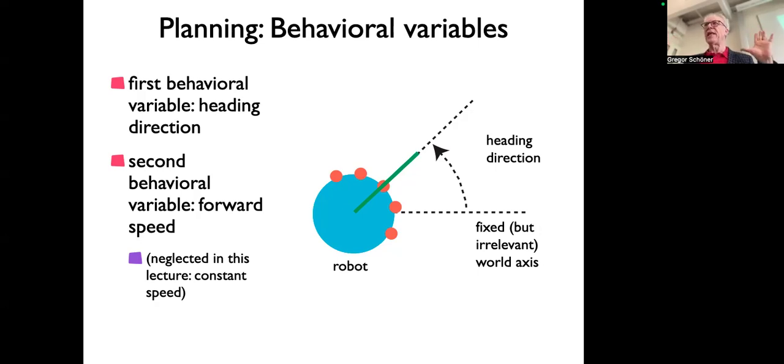That's kind of an important thing, it turns out, that it is relative to a fixed world axis. So in particular, it's not an axis that's on the robot, right? That will be rotating with the robot. When the robot rotates, the axis relative to which you're measuring its orientation remains fixed. So think of it as relative to north to make that mental picture easy.